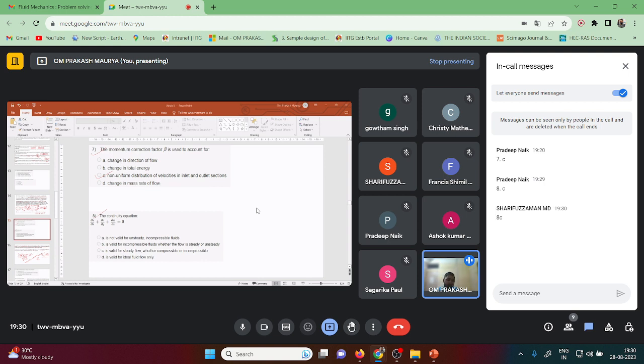Here the definition is required. If you know the definition of compressible or incompressible: in case of compressible flow, the density is not constant as the flow moves in the flow domain, but in case of incompressible flow, your density is constant. So in incompressible flow, you may not consider the density in the equation. So you can think like that and give the answer.